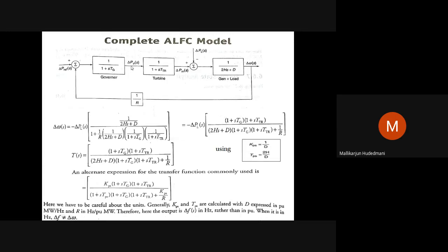And the turbine takes this variation in the valve open and close as a mechanical input supplement. Valve means resource control. This will accelerate or decelerate the turbine to develop additional mechanical input to the generator, or regulate it. That's how the turbine transfer function, on the change of valve position, develops the change in mechanical input.